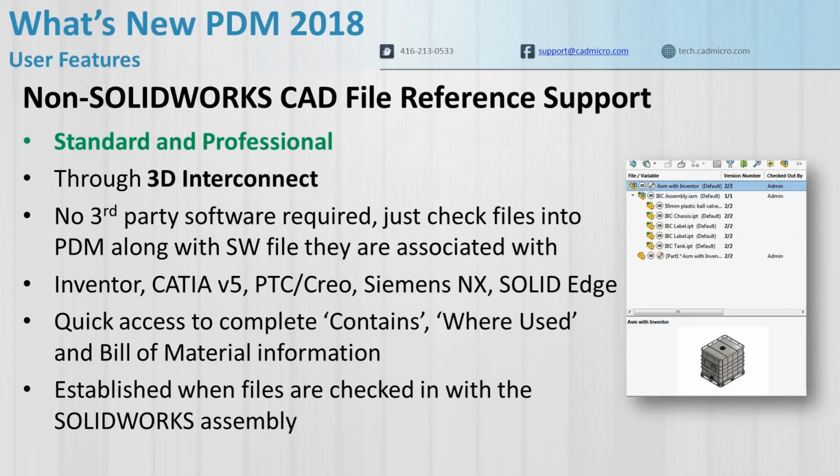Non-SOLIDWORKS CAD file reference support. For the folks out there who are working with Inventor, Solid Edge, Creo, and that sort of thing, you can now manage that information and the references in PDM. This is done through 3D Interconnect for those of you who are using it. So you create your references. If you look at my little screen over here, I've got a SOLIDWORKS assembly, but it's actually referring to a bunch of Inventor parts.